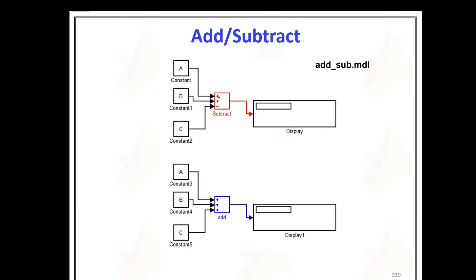Simulink. Just I am adding a plus b minus c. This is constant. This is not matrices. Don't think it is a matrix. It's a single constant A, if you want you can increase it. You can double click this subtractor. This is one block. This is another block in sinks, and this is another block, commonly used. This is another block in sinks, and this is another block in sources. If you want to increase, this is the 3. The parameter is the 3 here. If you want, you can go ahead with 5, 6, 7, 8, 9, 10 like that also.